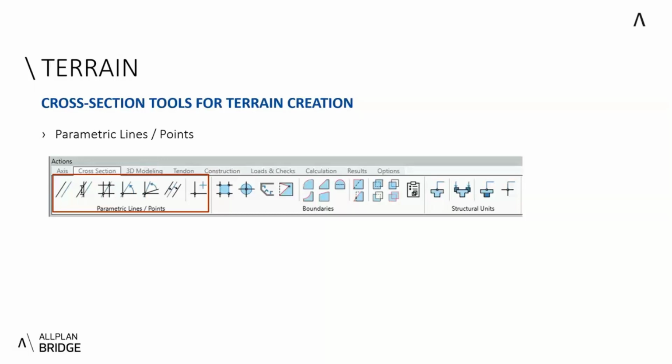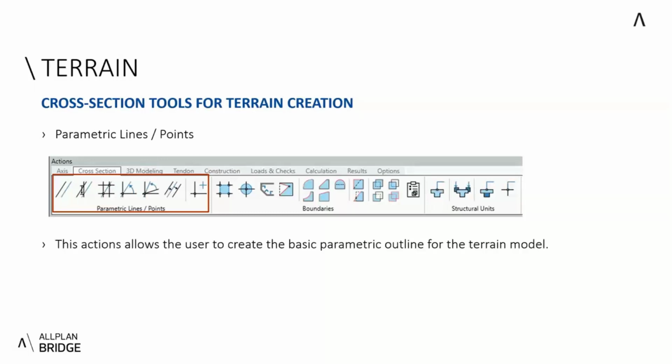And there we have all sorts of functionalities, where we go from parametric lines, where we can place a parametric line over a direction, a parametric line between 2 points, different types of line per angle, line by relative factor, or by just placing a parametric point.